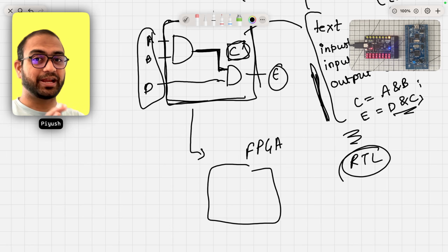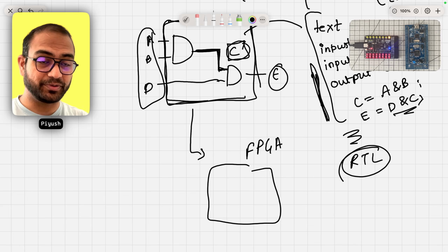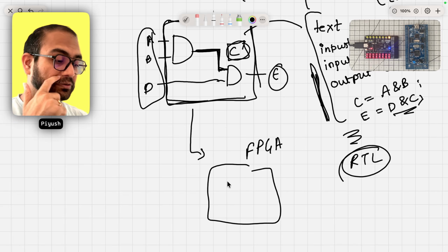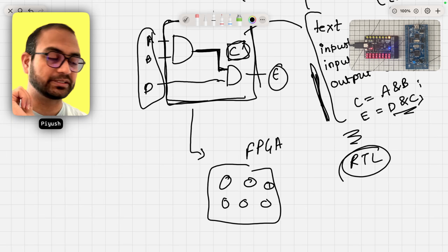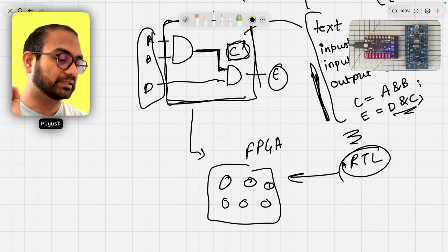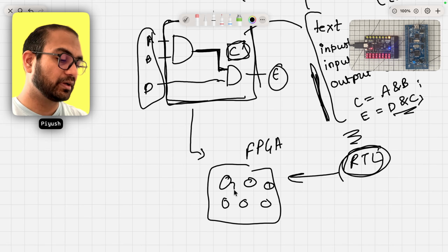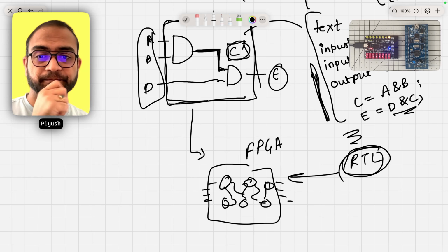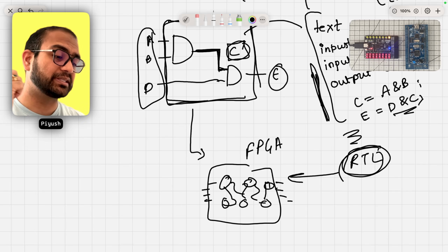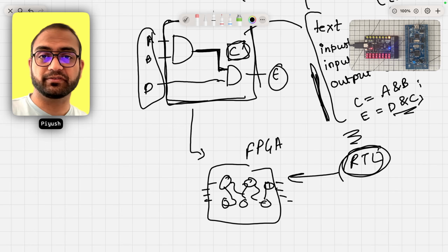So what we are heading to is that an FPGA can become a CPU. A CPU cannot become an FPGA. Given that an FPGA has unconnected hardware units, you can say, let's take this RTL and see if the same circuit, realized by an FPGA, is well behaved. I can run my tests on that. And once I'm convinced that this hardware circuit is working as I'm expecting, I can send it to the fab.